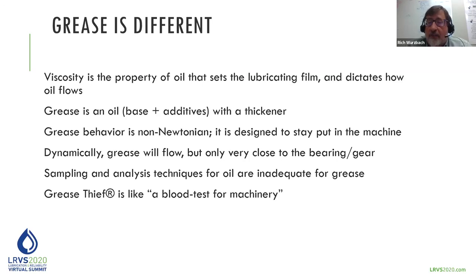If we get further away from that close location, we are now in a zone of the machine where grease really isn't moving. It's not being updated with the current status of the grease itself that's doing the lubricating, or of any contaminants that are present, or any wear particles that are being generated.